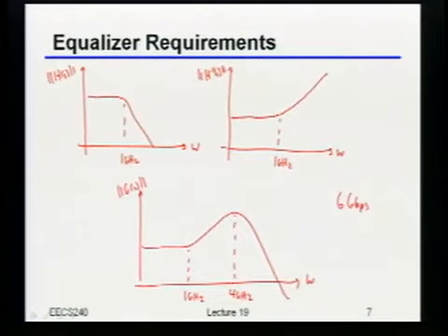Now there's something we need to be careful to notice here. That point right there actually has two poles, not just one. As we're going to see in a second, one of those poles has to do with the bandwidth limit of your amplifier. Because beyond a certain frequency, your amplifier can't get anything through it.